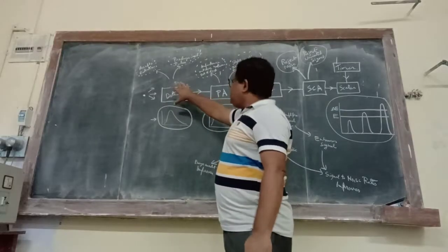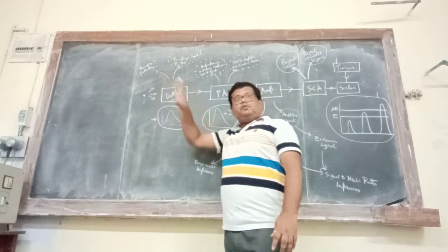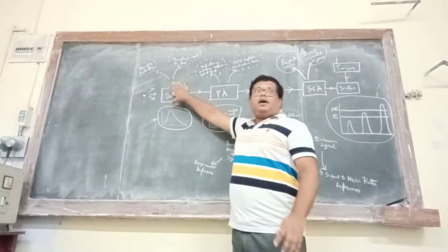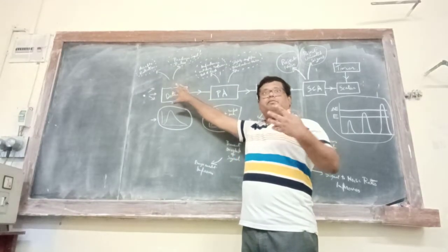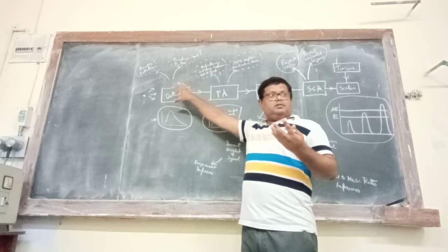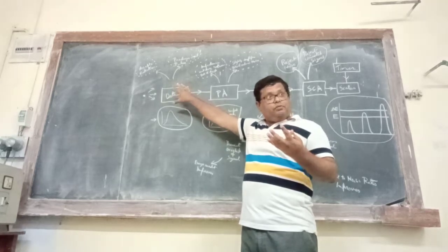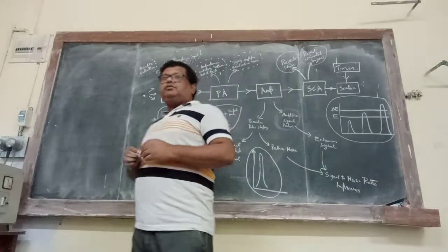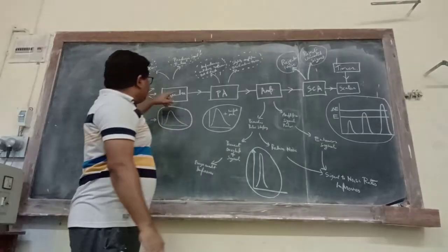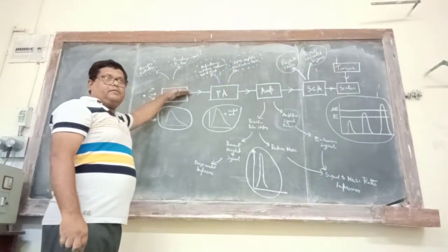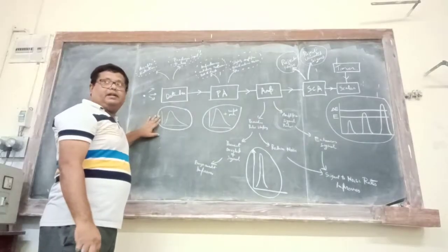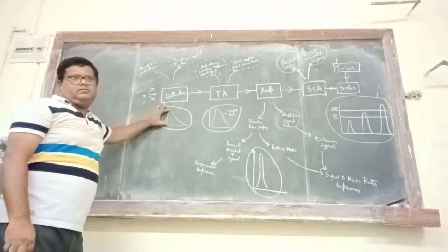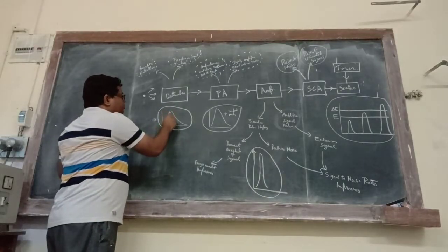So the main job of the detector is to produce the signal, and now we have to make the signal usable for us, so that we can extract the information about the radiation particle. Okay, good. So how do we start? The first thing to know is that when the signal exits the detector, I have shown the representative diagram over here. The first thing is, this amplitude is very small, say of the order of millivolts.